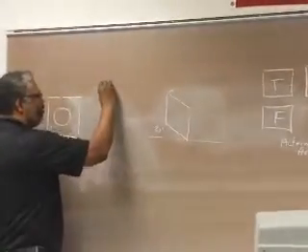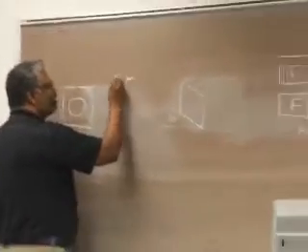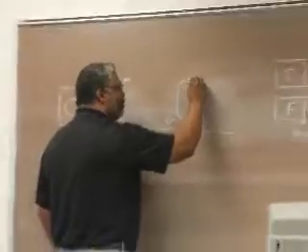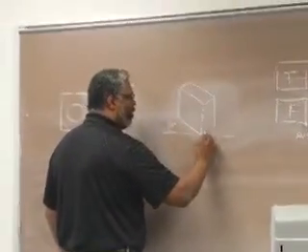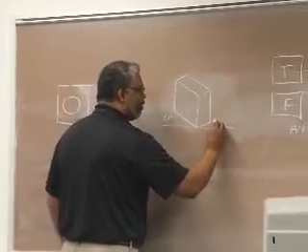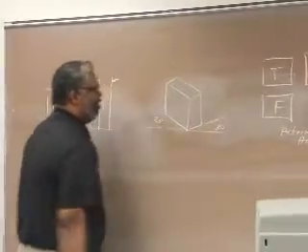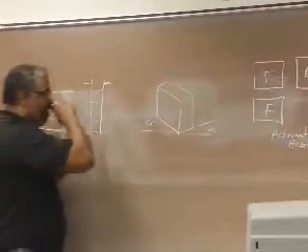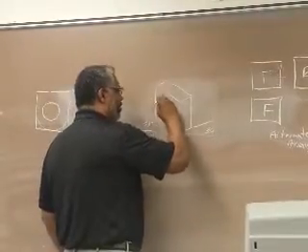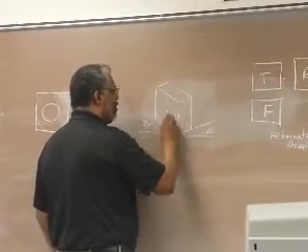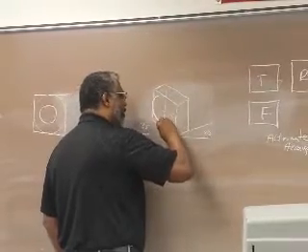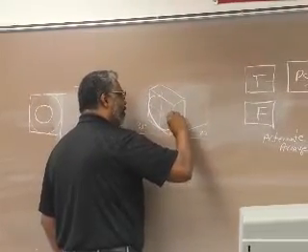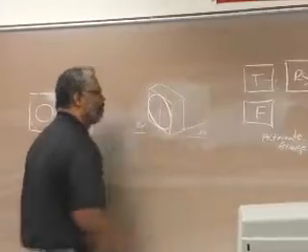And then if we take that distance here to produce that thickness, then we will wind up with that. So we got a square here, like that. Now if I was doing this on a board, then I can locate the center of that right there and construct an ellipse that runs tangent to the quadrants of that, like so.